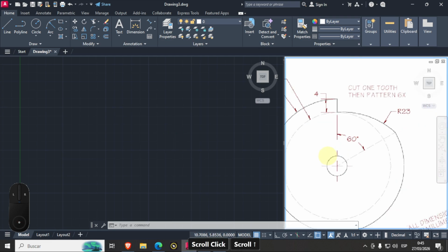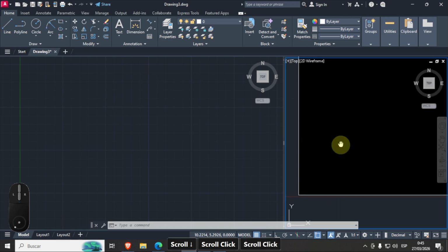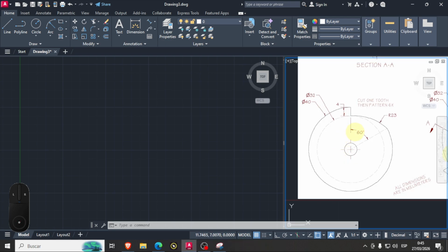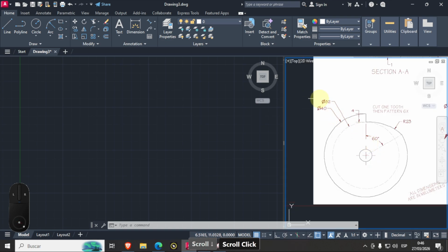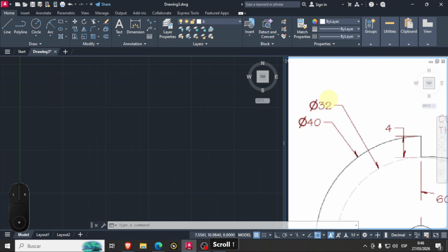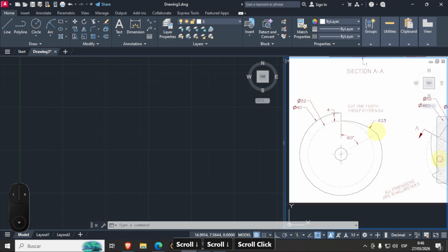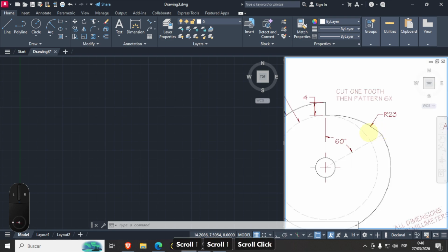First things first, let's see that in here, to create the spinning wheel, I don't know what's the name, to be honest, we have to create different circles and an arc. For example, we see that in here, the outer circle has a diameter of 40, while the inner circle has a diameter of 32. Also, here is this arc in here that has a radius of 33.